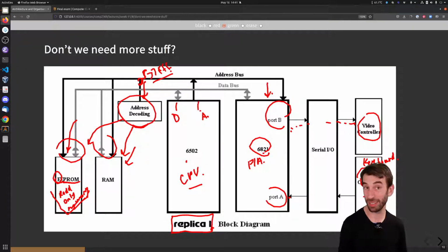It's pretty old technology. This is stuff which was developed in the early 70s, late 60s, before Flash was invented. So if these people had Flash, there is no way we would be seeing that weird old programmable ROM. You'd definitely have a Flash chip that you can just electronically rewrite, just like the Flash non-volatile storage on your microbit. But because that wasn't invented yet, we had this other technology, which at the time they thought was super cool, because it was a kind of memory that you could program once. It would never run out of batteries or anything, and you could carry your program around with you.